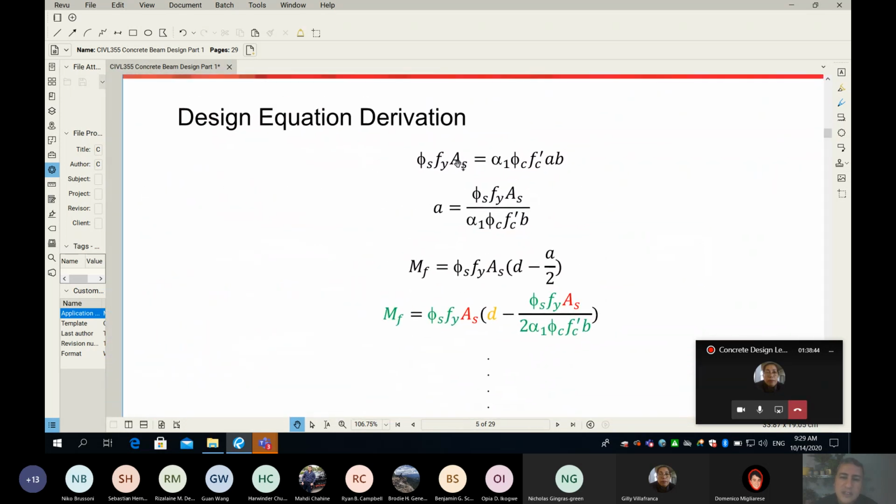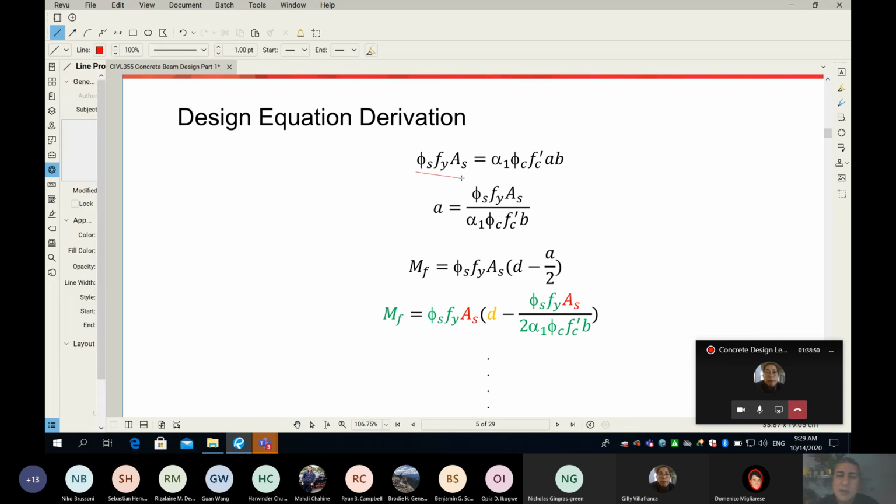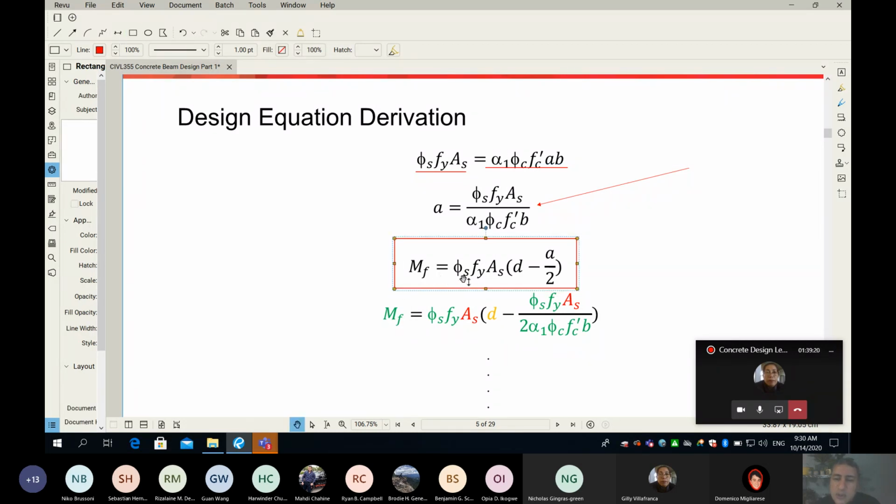Please watch this. I started here from T equal to C: total tension in my rebar equals total compression in my concrete. And from that, I got this equation here, which, if you finished assignment number 3, you have done at least 2 times. Then I'm going to write my equation for MR one more time. Guys, remember, in the check problem, if you've done assignment number 3, you've seen this equation. It says MR is equal to T multiplied by the lever arm. Nothing new. All I did is replace my MR by MF, because that's what I know.